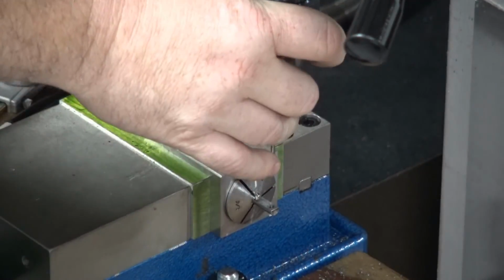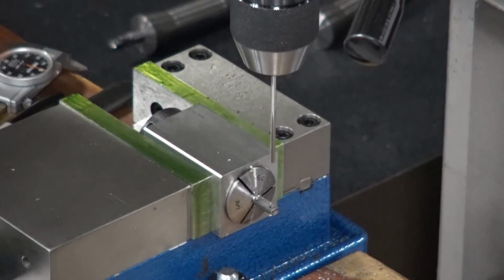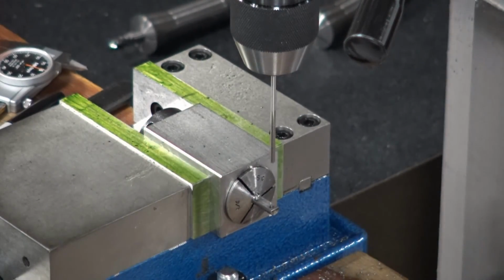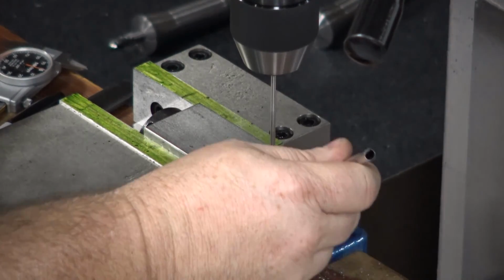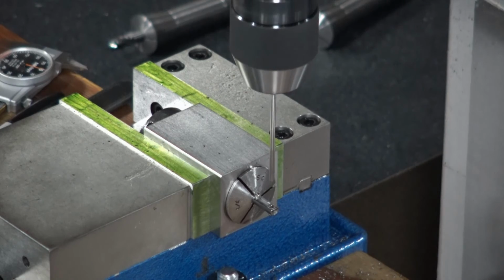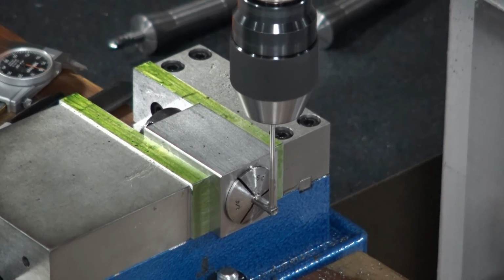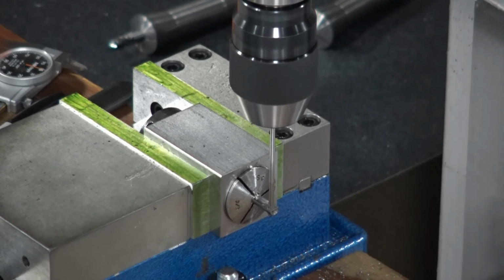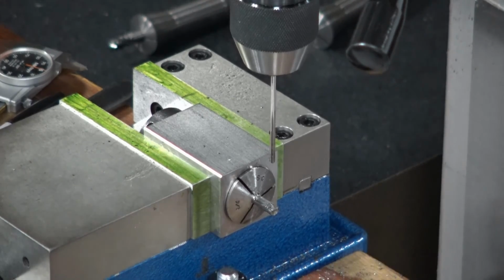Don't get to where you're moving too fast that you forget steps. So if we divide by 3, because this is a 6 fluted reamer, I'm going to be around the 700 RPM mark. So 700 RPM is really close to that 775. So we're going to be in low range. Okay, so now a nice and steady feed through. Feed back up out.